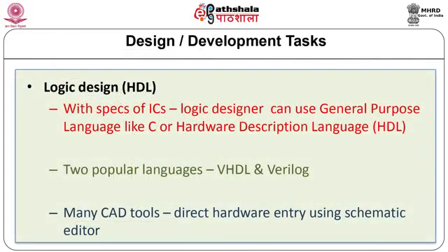Logic design HDL. As a first step in the design, there is a need to obtain clear specifications of the IC. The designer may begin with initial algorithm to be implemented in the hardware and work purely in the behavioral domain. Some designers use general purpose programming language like C at this level. On the other hand, more and more designers use popular hardware description languages, HDL, to implement the design.